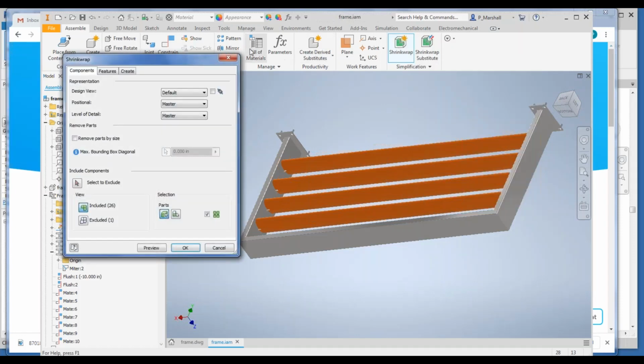and make it simpler. And there's a couple of reasons why you might want to do that. First, the manufacturing model is typically way too detailed for the architect. Making a Revit family with all of that detail will create an overweight, bloated object, which would impact the performance of the BIM model.